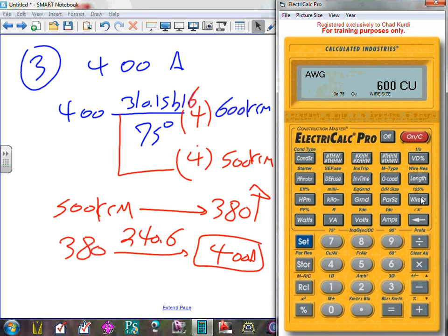Feeders. Okay. Now, what if we have to derate based on temperature, because we're in the middle of the desert in Arizona, and we're pulling this feeder? What if we have to derate based on temperature and or based on bundling? Only a fool will bundle these things together in a conduit. It's really feeders. But temperature could happen easily, right? I could parallel these. In this case, I'm not paralleling, but I could have 10 sets on the top of the roof going to an air handling unit, right? I could have that one outside, ambient temperature is high. So I could have a situation like this.